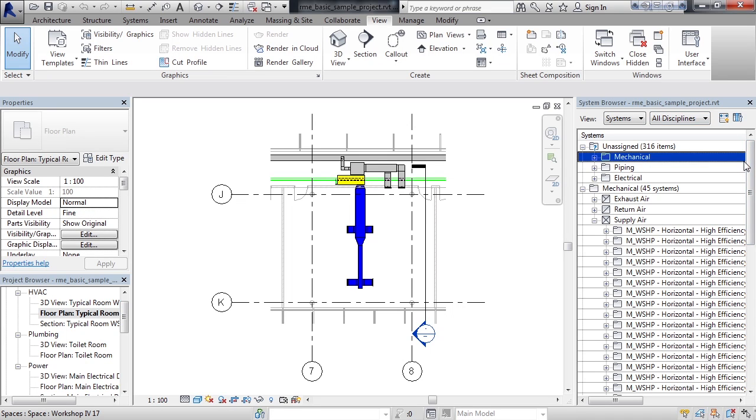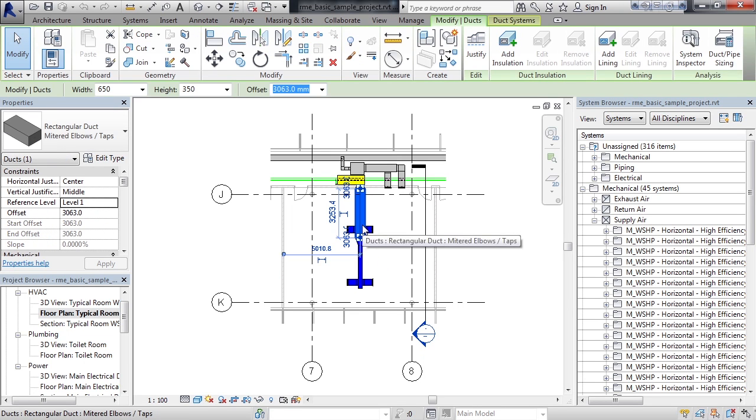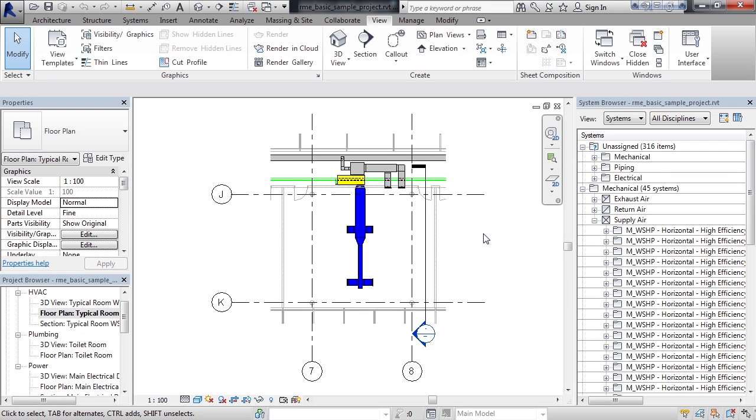Now, if I wanted to look at the system that's on my screen and its properties, for example, the elements in blue, obviously you could just go over that system and click on it. It would highlight and you would see those elements on the panel in the left in the properties area. But let's use the system browser for this. So if you've clicked anything, just click off of those elements in the white area so nothing is highlighted.